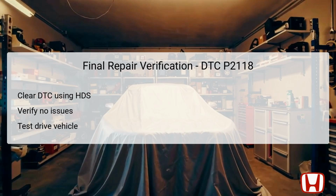After completing the necessary repairs indicated by the troubleshooting steps for DTC P2118, it is crucial to verify that the problem has been fully resolved. The first step in this verification process is to clear the DTC using the Honda Diagnostics System, HDS, to reset the vehicle's monitoring systems. Following this, the technician should perform a detailed check to confirm that there are no lingering issues associated with the throttle actuator.